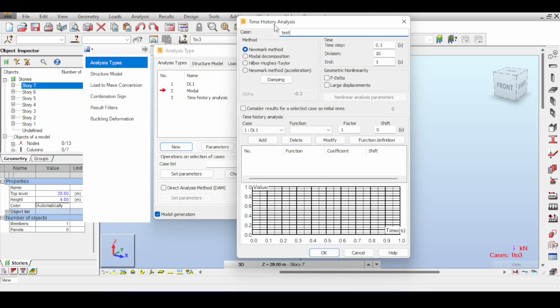modal analysis using the orthogonality of modes, and this is something I will leave for you, dear viewer, to think about. This analysis using the mode shapes is basically called modal decomposition. Of course, there is much more than this, but I'll basically go to Newmark's method, the time step method.